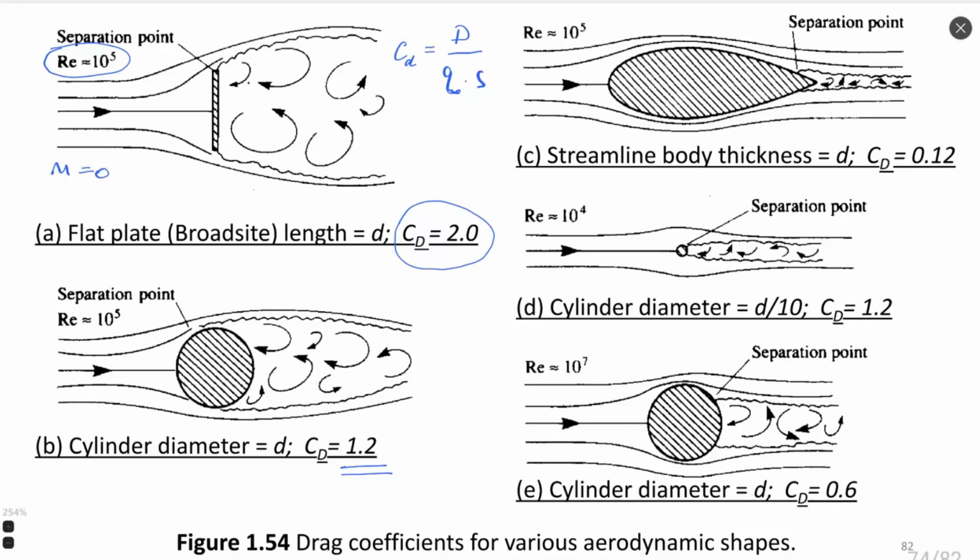It happens because a cylinder has better flow organization, and turbulence intensity behind the cylinder is much smaller than behind a flat plate. It's smoother from the point of view of flow, and flow goes around this cylinder in a better way. So it creates a smaller volume of intense turbulence inside.